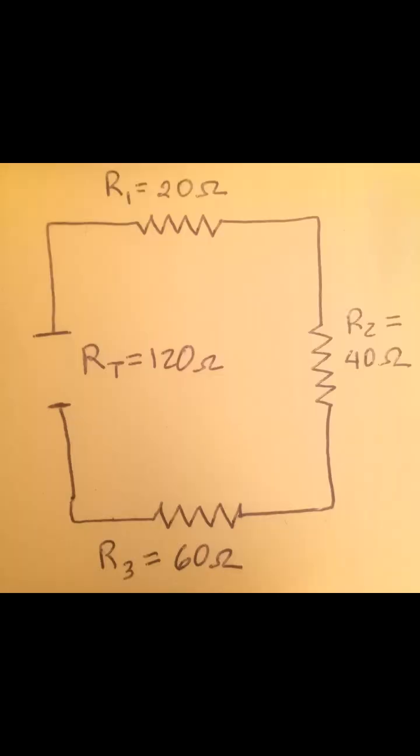Resistance in a series circuit. Total resistance in a series circuit is equal to the total circuit resistance combined. By adding the value of the individual resistors together, we find the total resistance of the circuit. See the figure 6-3, where resistance total, or RT, equals resistance 1 plus resistance 2 plus resistance 3, and so on. Figure 6-3 consists of 20 ohms, 40 ohms, and 60 ohms resistors connected in series. The total resistance value for this circuit is 120 ohms.